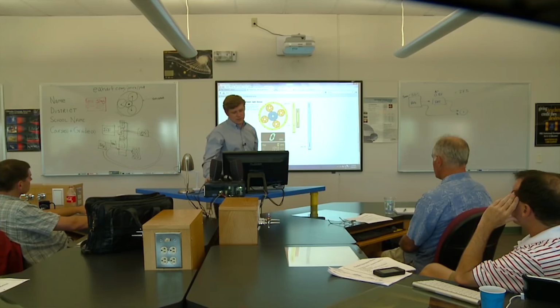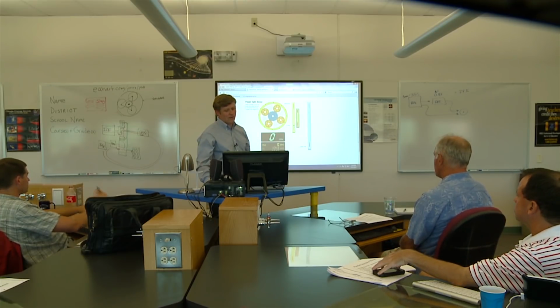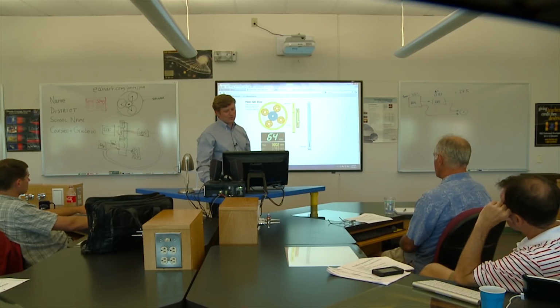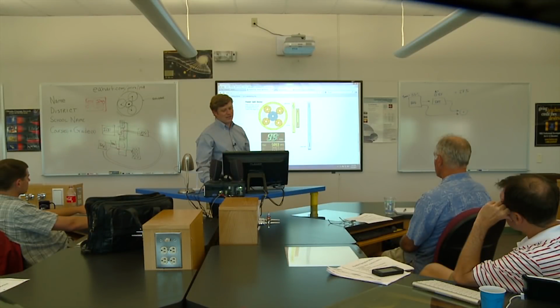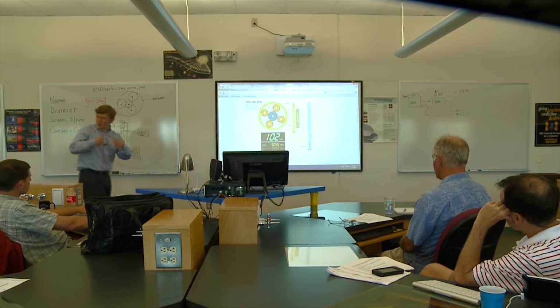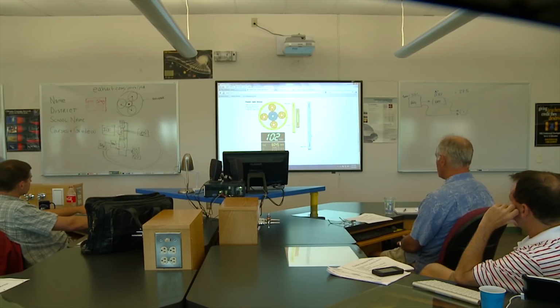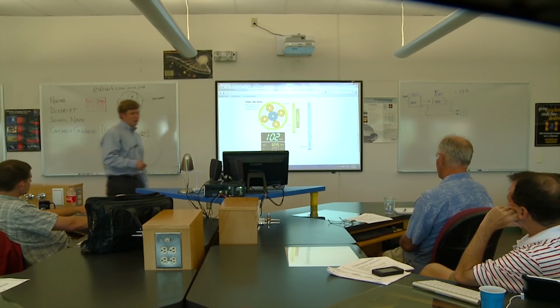So let's try to figure out how fast a Prius can drive. First of all, let's try to make the engine go as fast as it can. Here's the engine at 3,500 RPM, and I'm reaching the red line of the engine, and the generator is spinning as fast as it can backwards to try to get the speed ratios to all work out right. But that's how fast the car can go.